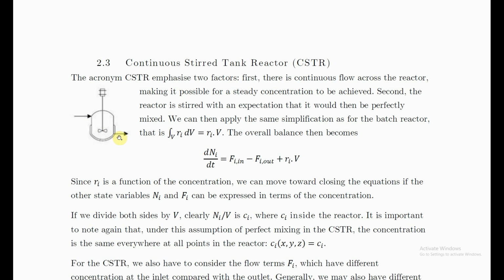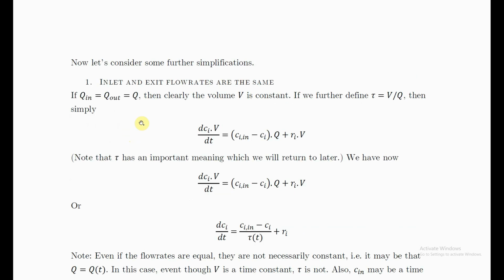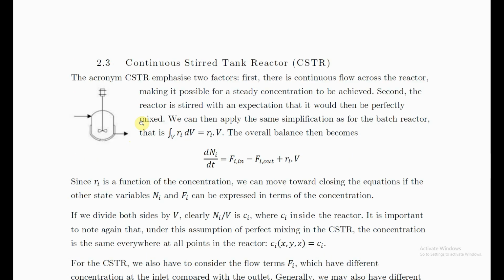We can still form our product. We are still converting a reactant to a product, even though we've reached a kind of constancy here. So if we are feeding, let's say, 50 moles per second of a reactant here, and we are getting 40 moles per second of product out here, plus maybe 10 moles per second of unreacted reactant, then that can all happen steadily.